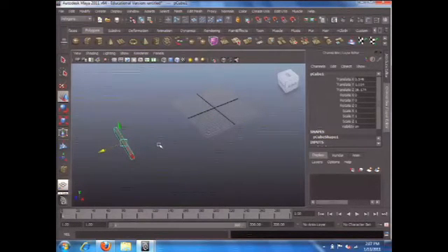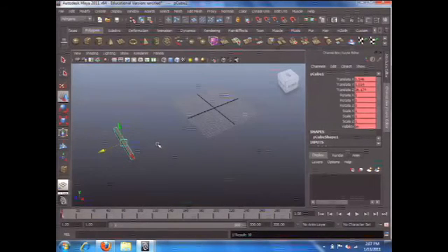And then I'm using a hotkey on the keyboard, S, to keyframe all the values. So S means save the keyframe. You can see what happened is all the channels became orange or purple. That means this channel has been recorded into the time slider. You can also see at frame 1, it shows as a red frame marker. All right. So these features are all associated with the object. In frame 1, that's all of these values.